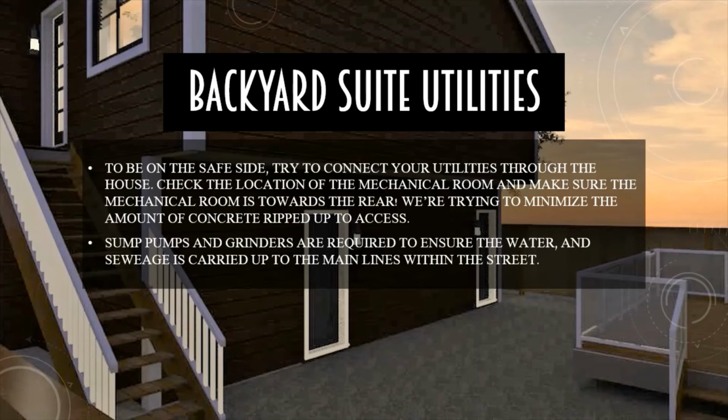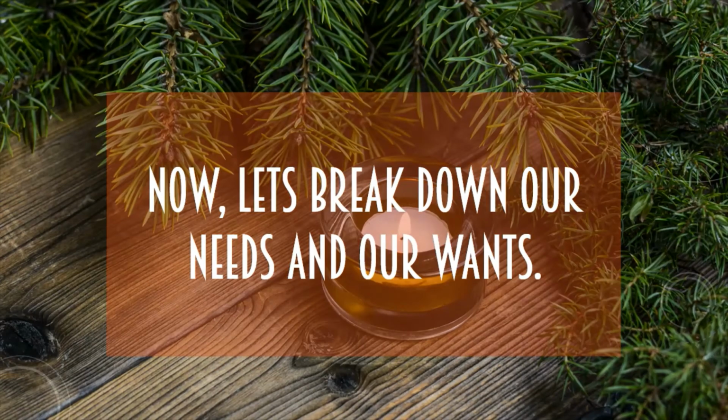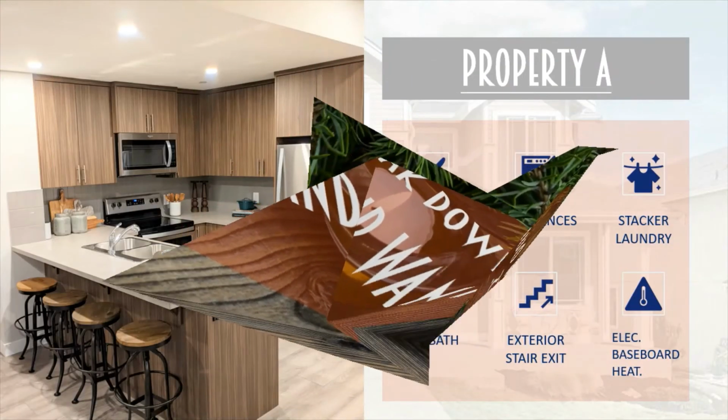Another thing you also have to think about are sump pumps and grinders, because you have to understand your suite is probably going to be at a different geodetic elevation relative to the main house. It could either be higher or lower. And depending on where the elevation of the main street lines are, you're going to have to use a sump pump or a grinder to make sure that the water and sewage is pumped all the way out to the street and having no problems with any forms of backup that can cause a lot of issues within your suite.